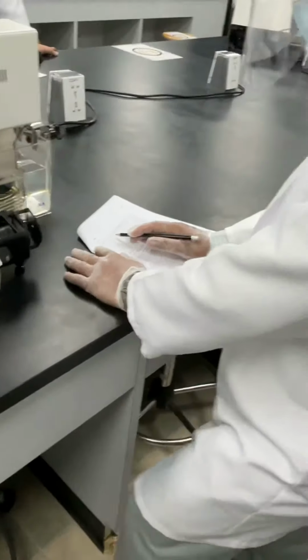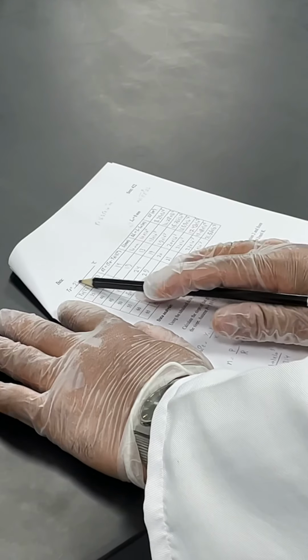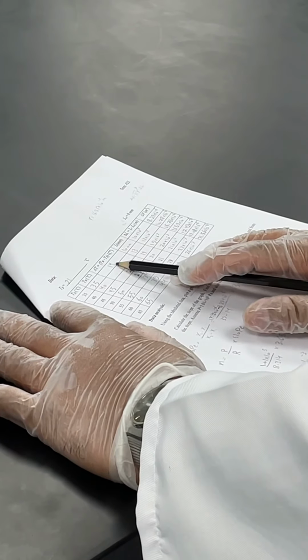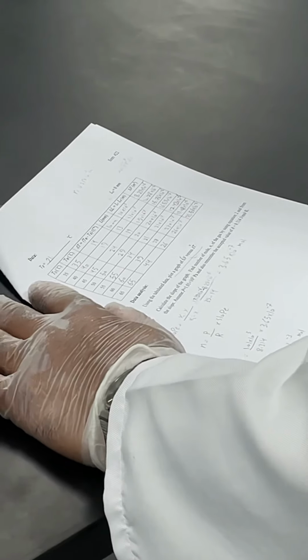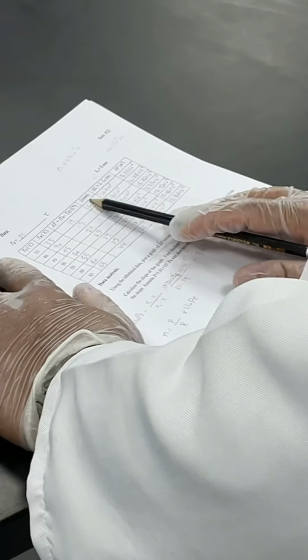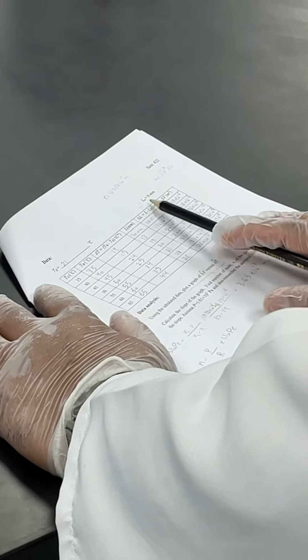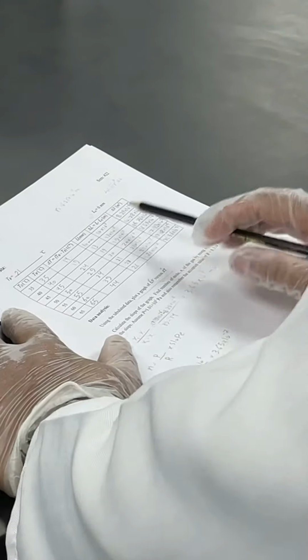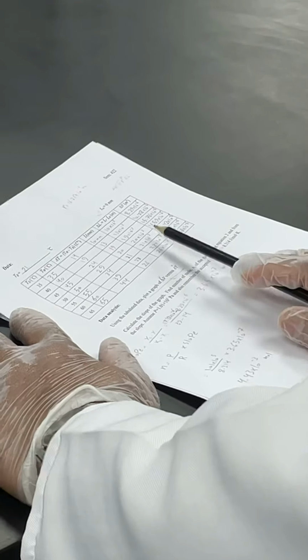Come to this. Delta T is equal to TW minus TB. This is TW, this is TB. You can calculate delta T. Delta T in Kelvin or Celsius will be the same, because it is the difference in temperature. And L is in millimeter. I want to calculate delta L. Delta L equal to L minus L0, L0 the initial length equal to 0. So I am expressing this in terms of meter. Convert millimeter into meter.